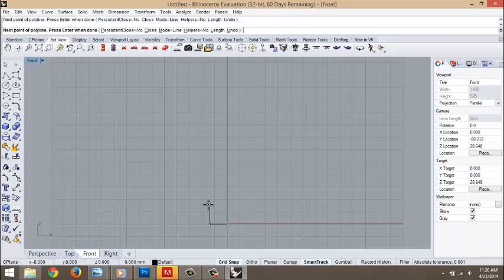Click that. Now you can double click, using the right mouse key. So right click on the mouse to show the line. It sort of looks almost like a little snake there. This is going to be the base of the rocket where it sticks inside the rest of the rocket body. Now we're going to draw the rest of the nose cone.